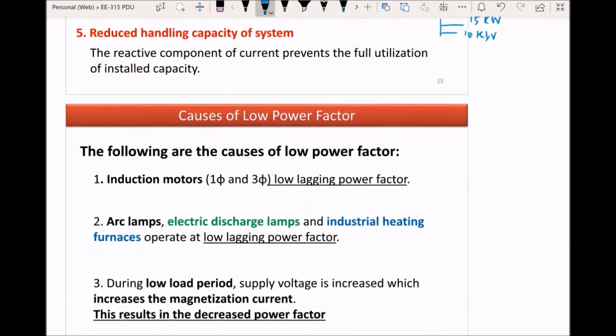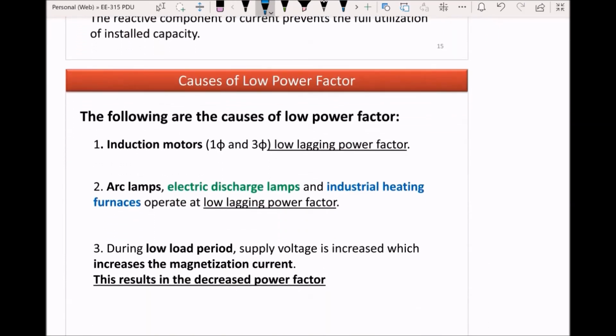Now, as described earlier, power factor is quite significant when it comes to designing a power system. Engineers usually get preloading information, and based on that, generating units and transformers are decided to be connected. Let me tell you another thing: the practical loads usually connected to a power system have a power factor of less than 0.8.